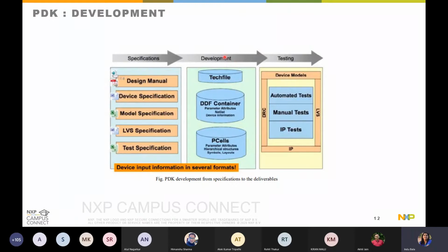During the development, yeah, these are some of the things. There are other attributes also. We create tech files. There are different kinds of tech files. It can be a tool-specific tech file. It can be a DRC tech file, which we also call rule decks, like DRC rule deck, LVS rule deck, EMIR, or electromigration, rule decks. So different kinds of rule decks, or you can have your LEF files, technology LEF files.